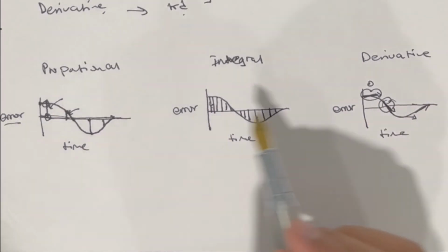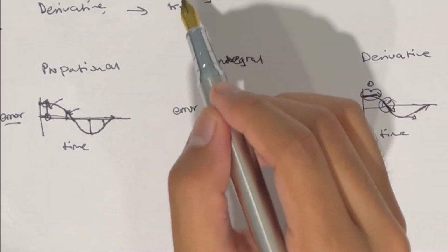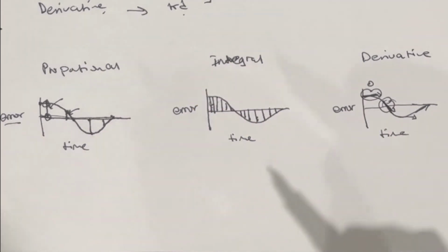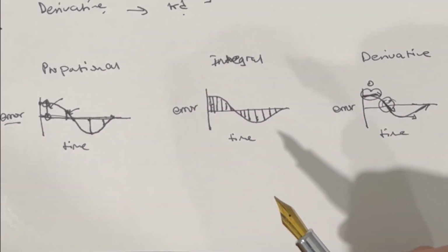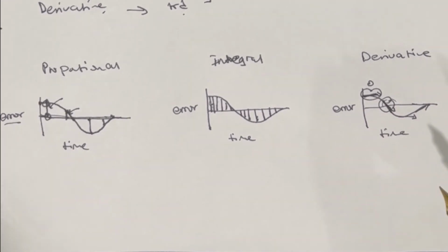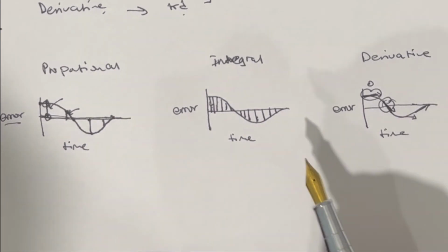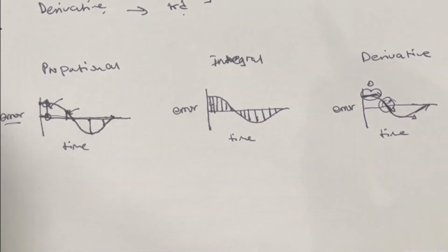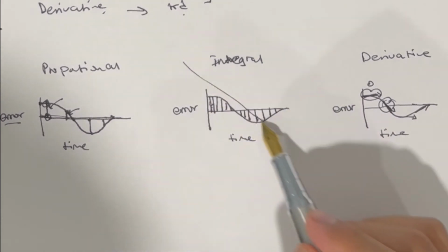So when you individually multiply these three errors with Kp, Ki, and Kd and sum them up, you end up with speed change, which is the amount that the robot is going to change its speed by. And so when it comes to line following applications, many people aim to have a PID line follower, but realistically from my experience, you generally don't need the integral part.